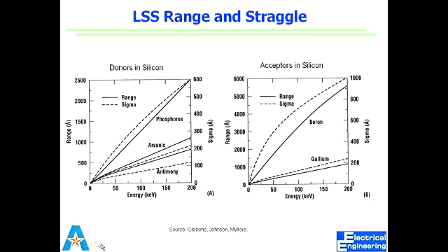So all you would have to know is how deep you want it to go and what concentration you want. What mass material you can easily apply, right? And that would define your process, right? So these are again range and sigma. Of course, we see that in this case, the sigma does not change with the range of phosphorus. What can be a simple reason for that?